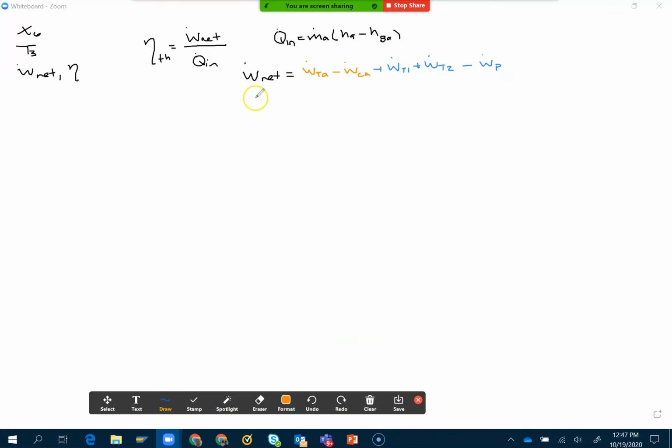Again, doing first law analysis, we can get that the power of the turbine of air will be the mass flow rate of air times the enthalpy difference. And since we have the isentropic efficiency, we should consider actual conditions.